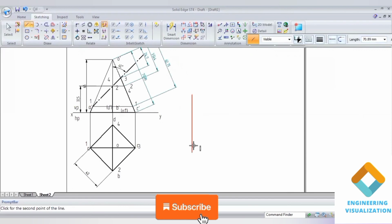After drawing a vertical line, we need to draw an arc using the arc by center command. Use the arc by center command here. Select the center point and then draw an arc. Again here we need to use the arc because the 40 mm length we need to cut.